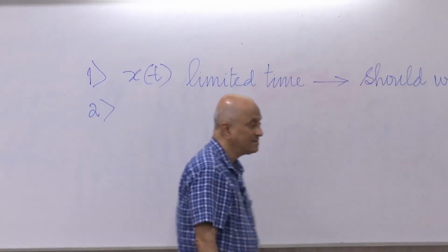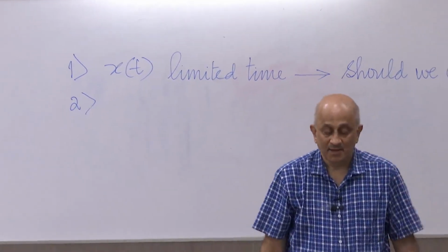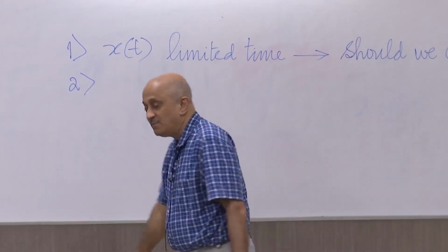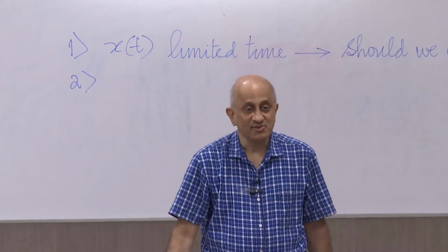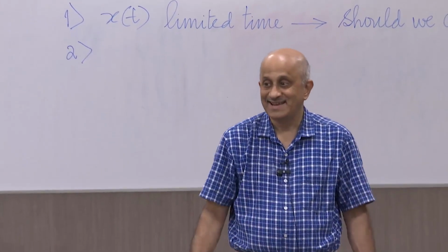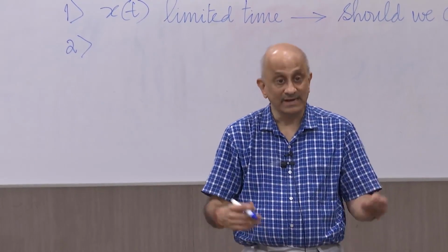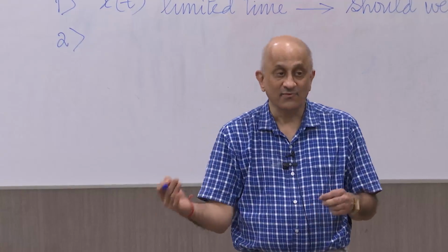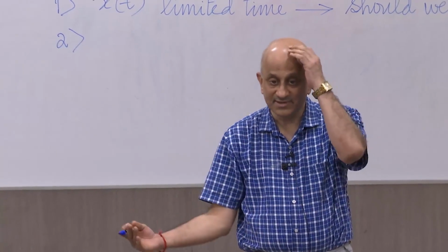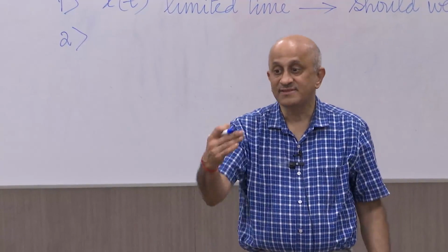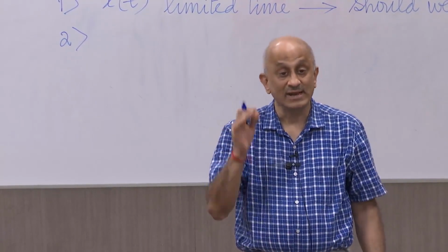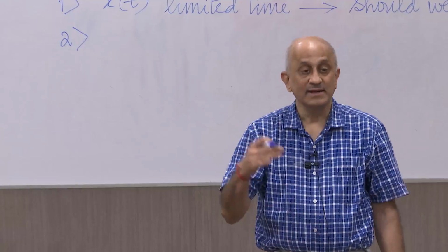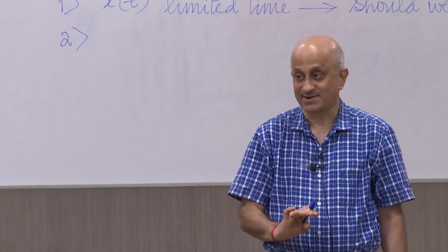The second thing is, what we did in the morning was to see what happens to one phasor. But now take the whole input in general. You obtain the output by convolving the input with the impulse response. What does this do in the Fourier domain? Can you look at the whole thing in the Fourier domain, if the input and the impulse response have a Fourier transform?